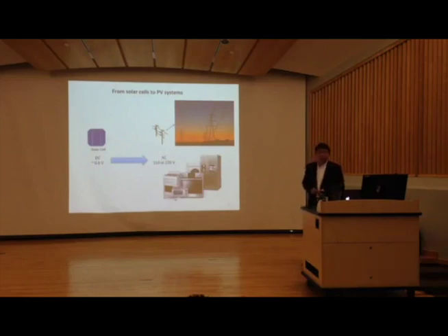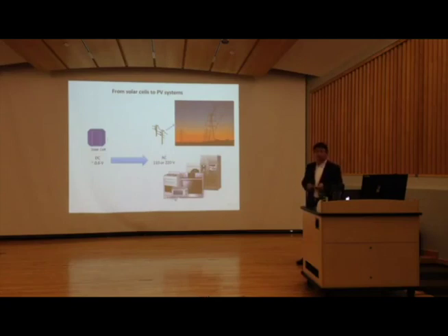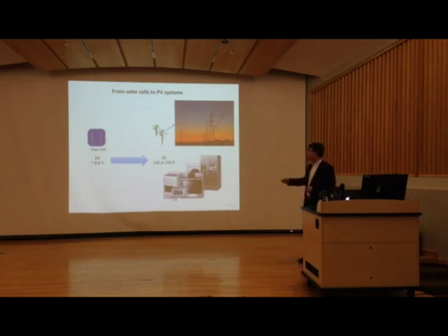And now I'd like to show you how to construct a huge PV system from basic solar cells. Because if you look at the solar cells, from the fundamental physics point of view, the voltage you can generate is only 0.6 volt, very small. And the current is DC current. DC current means the flow direction for current always follows one direction. But the electricity we're using these days is called AC, basically alternating electricity flowing in forward and backward directions. And the voltage is really high, 110 volts for North America and 220 volts for Asia and Europe.